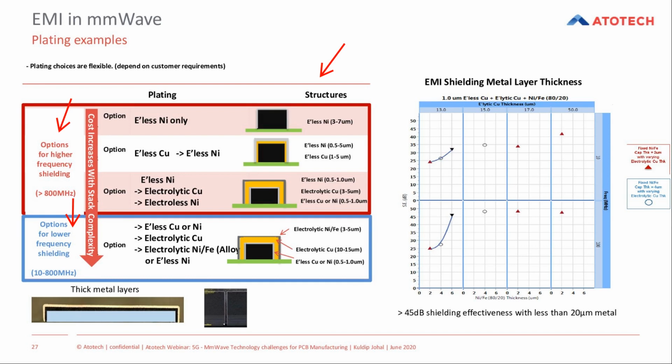At the lower frequency, the skin depth is larger and the conductance is increased and the current absorption is increased, which results in an increase in magnetic flux. Therefore, the metal and high permeability of nickel iron can be implemented to help redirect the increased magnetic flux.